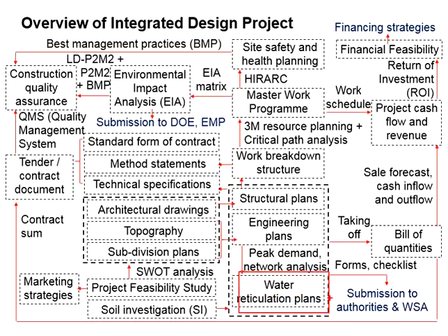The water reticulation plans provide the details and information of the water supply system, bringing the water to every single unit of the development project. You will need to clearly indicate where you're going to tie in the proposed water reticulation system with the existing water mains, so that the water can be supplied to the water reticulation systems. You also need to indicate where the fire hydrants, sluice valves, air valves, and so on are.